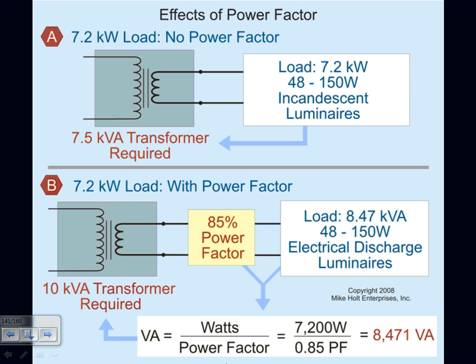So power factor, when we size electrical discharge luminaires, guys, volt amp, you always have to size, later on, when we do the power factor correction. I want to remind you from right now, especially when we go to commercial, when we size the conductor, when we size the circuit, everything is sized based on volt amps. If you don't have the volt amps, you need to go find the volt amps.